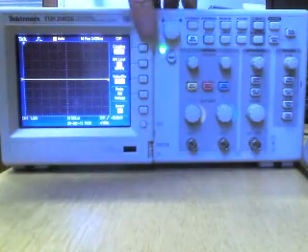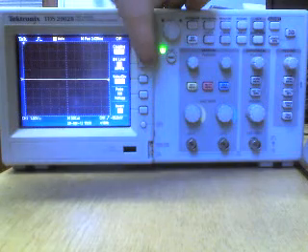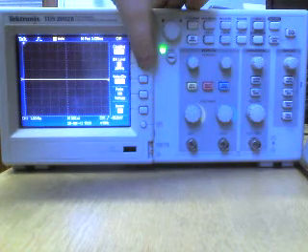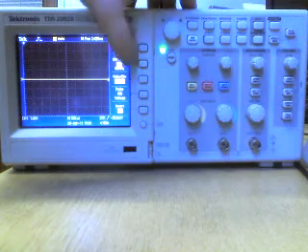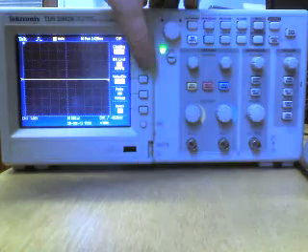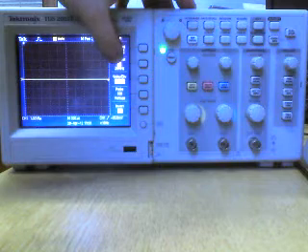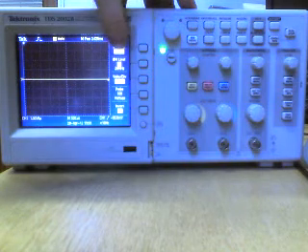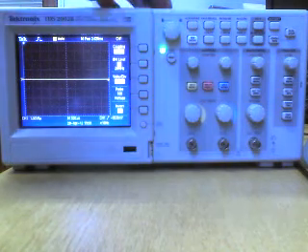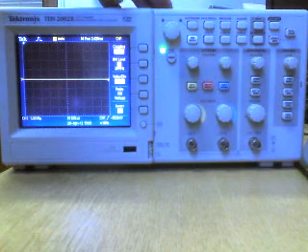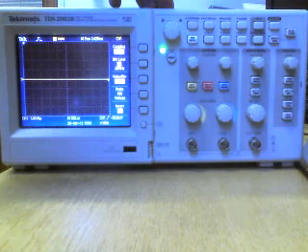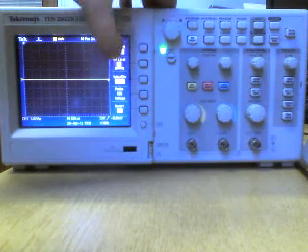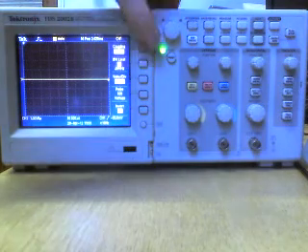Couple of extra things down here. We've got bandwidth limiting. You can either have it bandwidth limit on to 20 meg or off at 60 meg. This actually increases the resolution of the oscilloscope, so you can actually change it to a 20 meg oscilloscope essentially. And you have a much higher resolution, so it will use the rest of the value, your extra 40 meg bandwidth, and it will compress it all down into the 20 meg, so you get a much clearer signal.